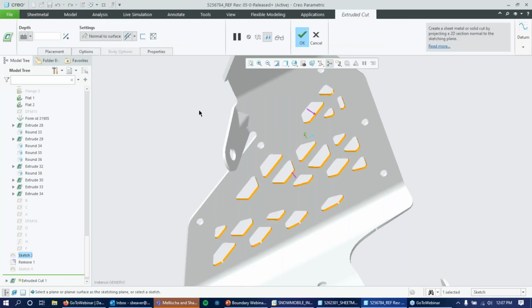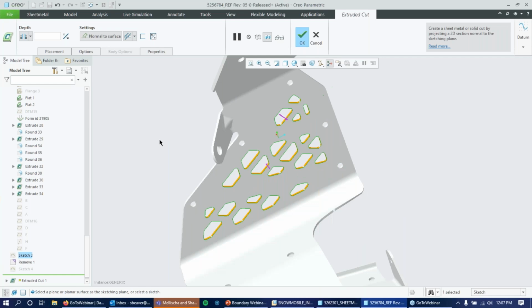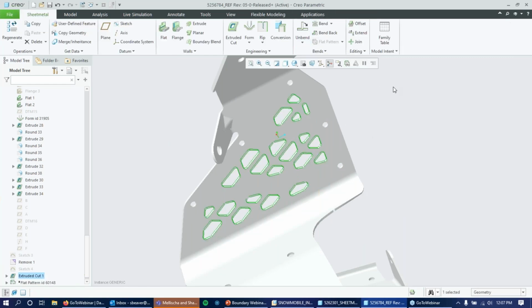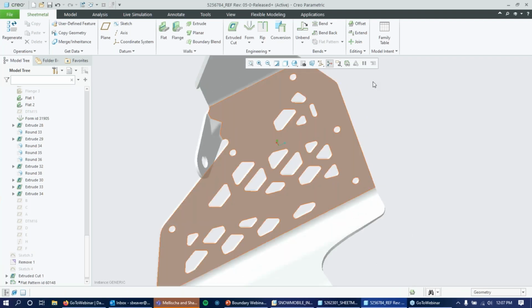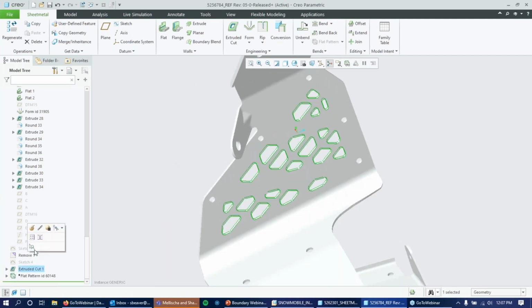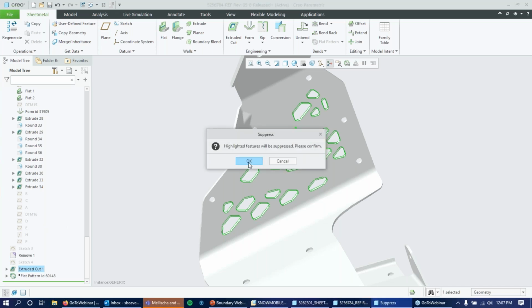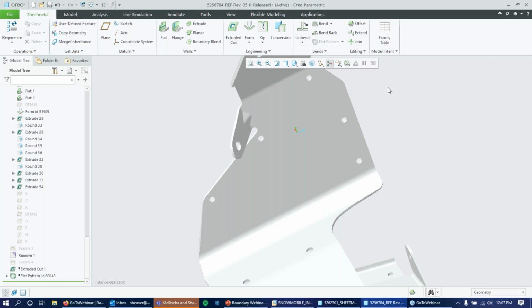So you'll notice if I click this, I have essentially the same options that I had in Creo. As I mentioned, the extruded cut feature is very, very similar to a remove material extrude that you encounter when creating a normal part or even a normal assembly in Creo. So I'm able to select through all, for example, make sure this is going through all my material infinitely in both directions. And I can click OK. So rather simple to do that. I'm just going to go ahead and actually suppress that for now. And I'm going to show you all how to create punch forms.